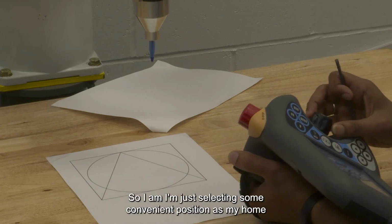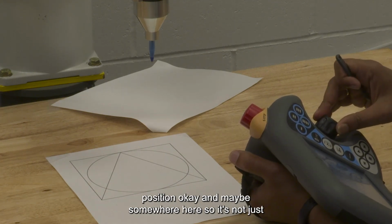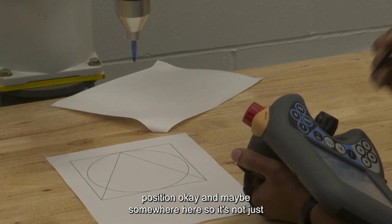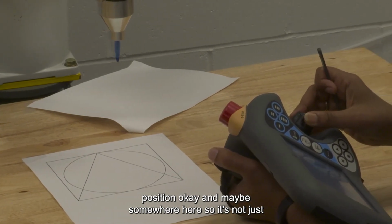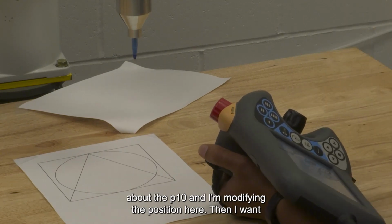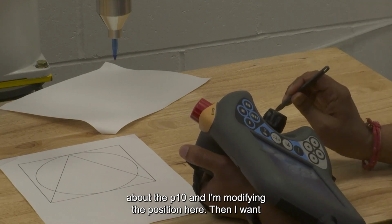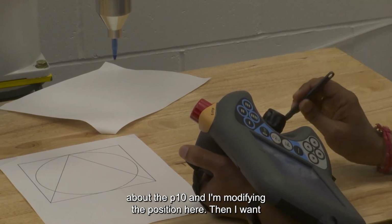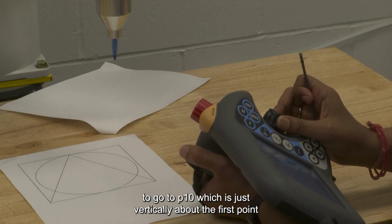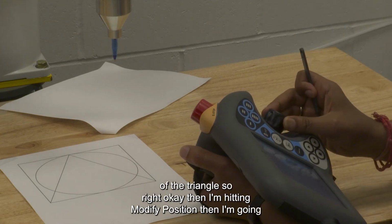So, I am just selecting some convenient position as my home position. Okay. And maybe somewhere here, so that it is not just above the P10, and I am modifying the position here. Then I want to go to P10, which is just vertically above the first point of the triangle.